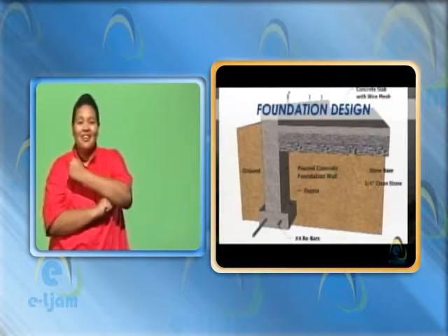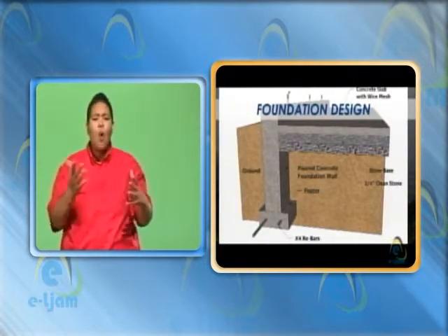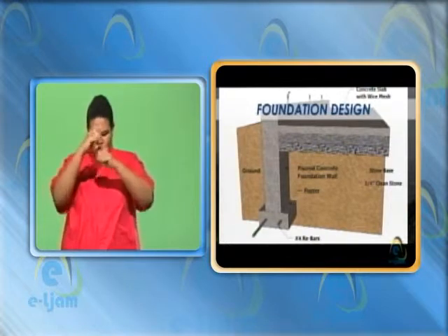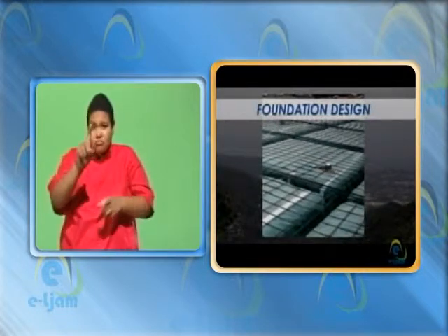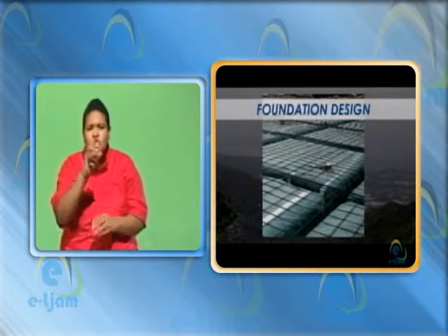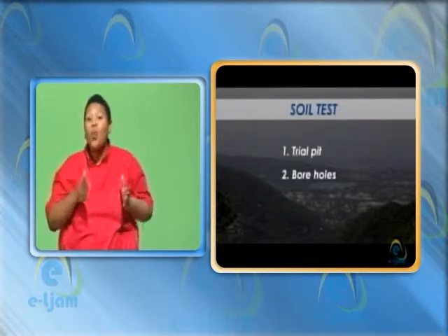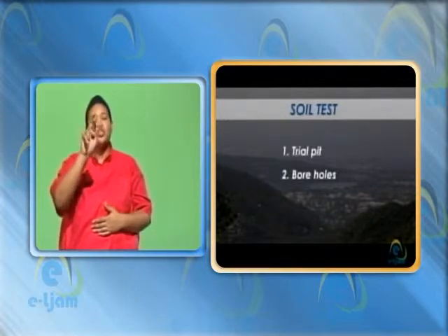For a building to remain firm for several years on the ground, it depends on the strength of its foundation, and in turn, the foundation design depends on the nature of the soil on which the structure will rest and the load which the soil is expected to carry. For this reason, it is very important to perform some type of soil test. The two main methods of performing tests are by trial pit and bore holes.